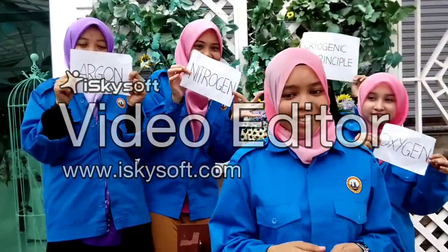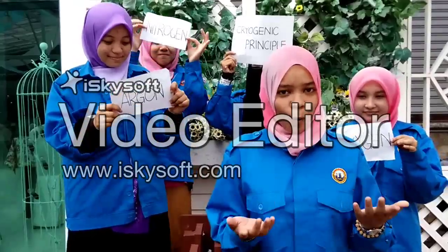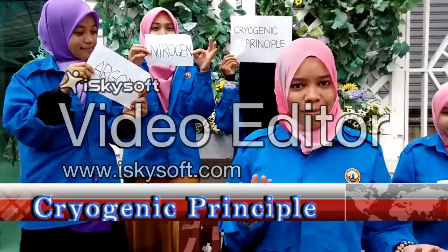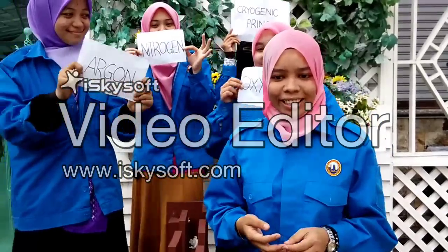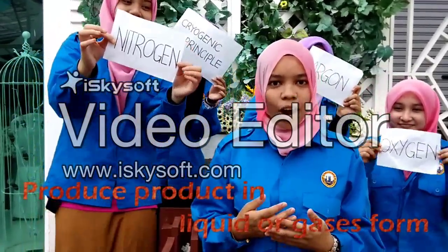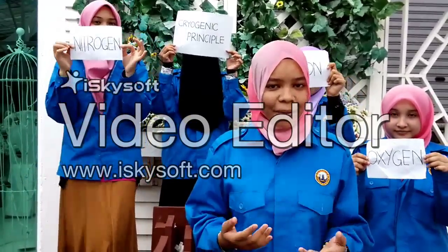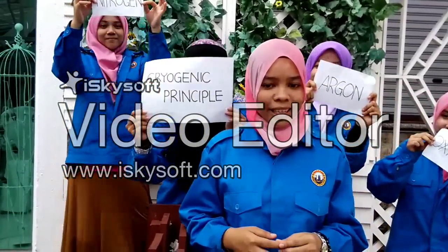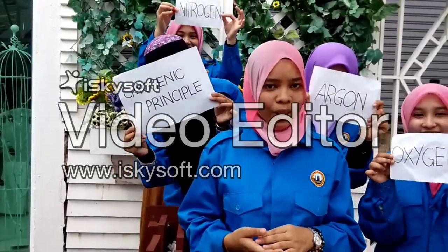Today we would like to explain the simple way about the separation process by using cryogenic principle in distillation process. What is cryogenic? Cryogenic is the study of production and behavior of material in low temperature. While cryogenic air separation is the most preferred technology for producing this material as gases and or liquid product and supposed to be most cost-effective technology for high production rate plants. In today's market scenario, all liquefied industrial gas production plants make use of cryogenic technology to produce liquid product.